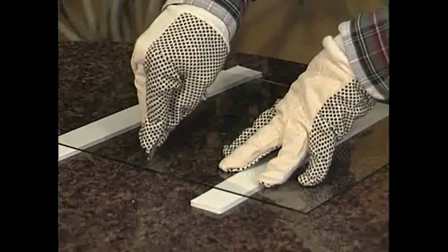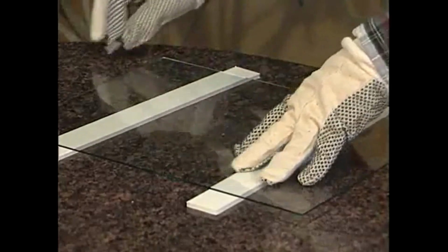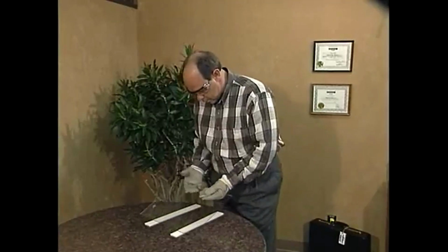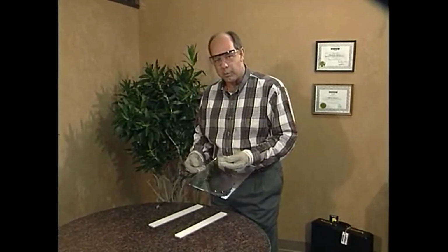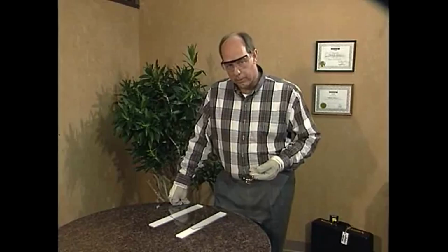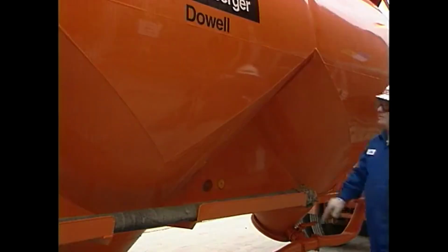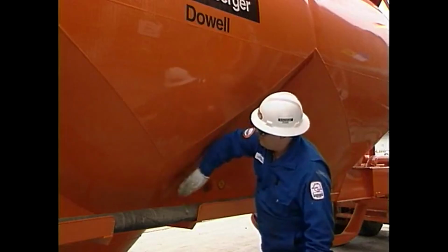Hammering is like scratching or scoring a piece of glass. Makes it easy to break. If you hammer on pressurized equipment, you have lost your respect for air pressure. Never use a hammer, even a rubber mallet, on a bulk material storage vessel.